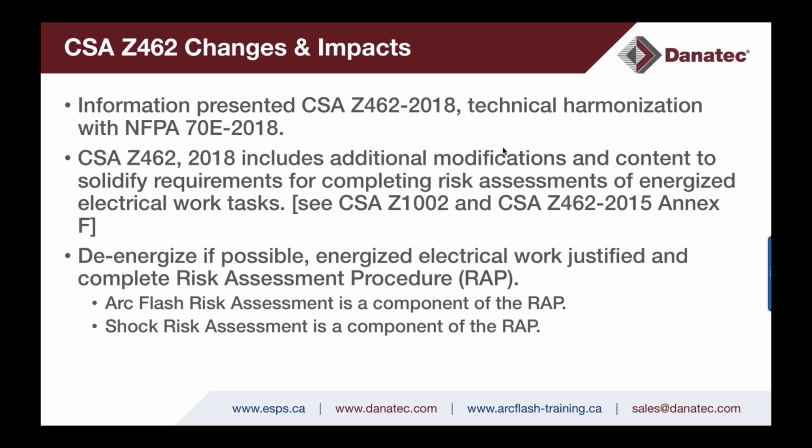Underneath that, the arc flash and shock risk assessments are separate, and they only provide additional protective measures to lower the initial or inherent risk level, when no arc flash or shock PPE is worn, to a residual risk level that will reduce the potential harm, or in the case of shock, eliminate the shock risk exposure with the application of rubber electrical protective equipment.